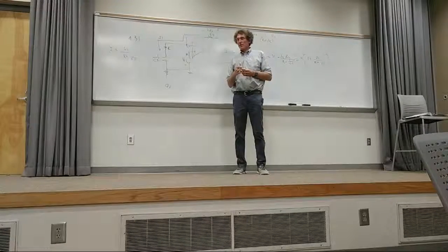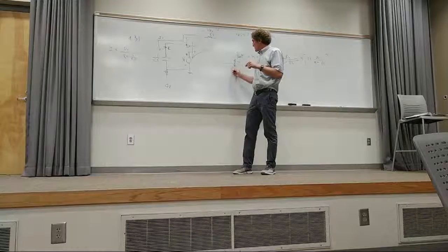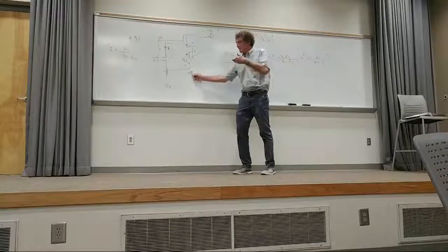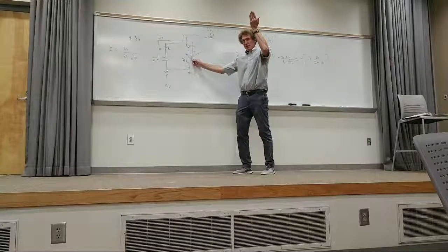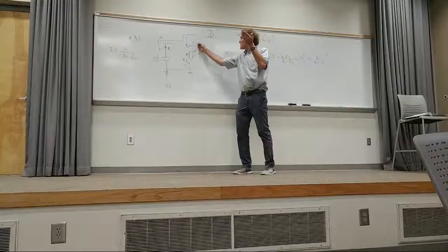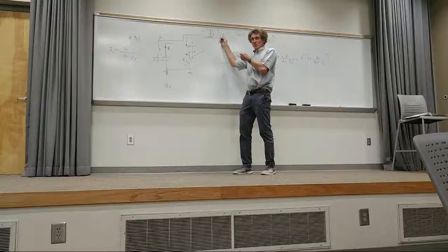So when it goes through the V1 and then it goes into that, it's not a V1 minus V1 thing? Well, if you start here at the negative terminal, if you remember how to do this in circuit analysis, you're coming around here, that's 0 potential difference. This goes from a minus to a plus, it's an increase. It's plus V1. And then it comes here, and from here to here, you'll notice it's minus to plus as well, right? So it's a voltage increase as well.